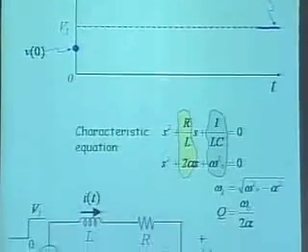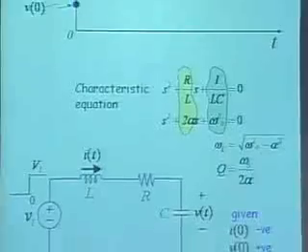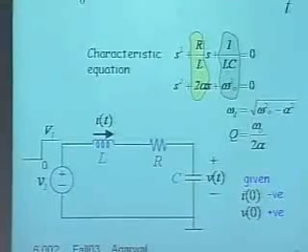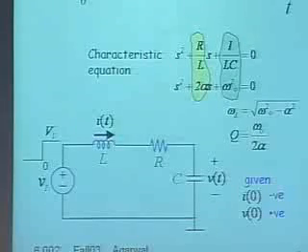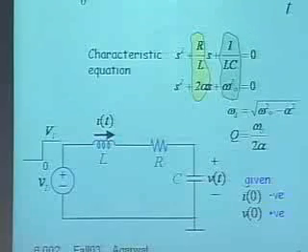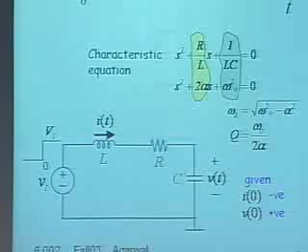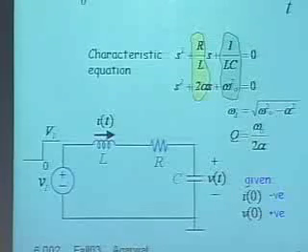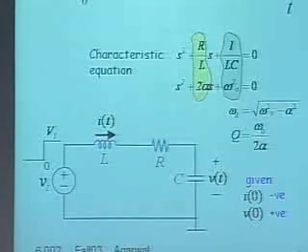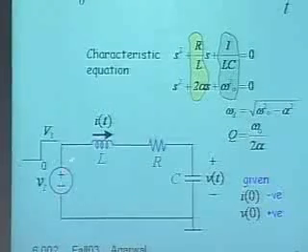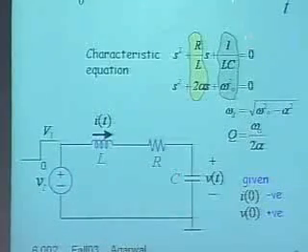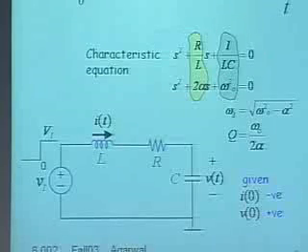So let's see. As a next step, what I do is I need to understand what the dynamics of the circuit look like here. So I develop the characteristic equation, and initially you'll write the differential equation and substitute e to the st and get this characteristic equation. But you can also remember it as a pattern. For a series RLC circuit, you always get an equation of this form.